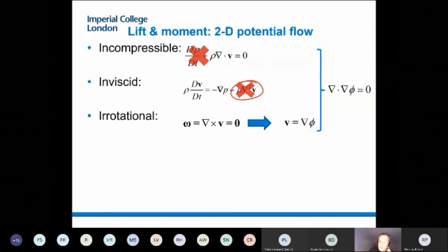So potential flows basically reduce the full Navier-Stokes equations into a very nice simple linear PDE on the potential flow function, which is Laplace's equation. It's an elliptic equation. It has very different features in terms of when you solve the problem numerically, and the key one being, of course, is that it is much easier to solve. Now, this is a stationary function, so there are no time dependencies, yet my airfoils are moving.